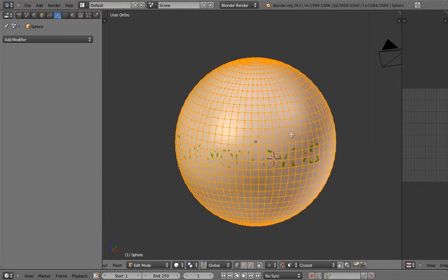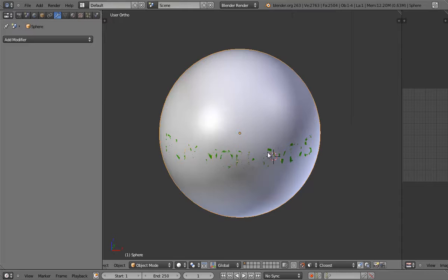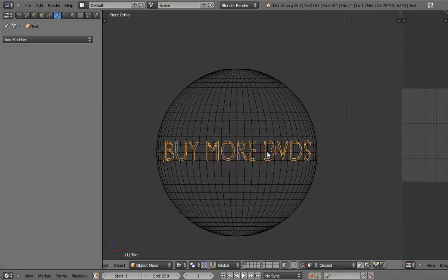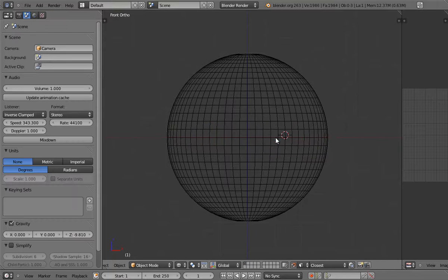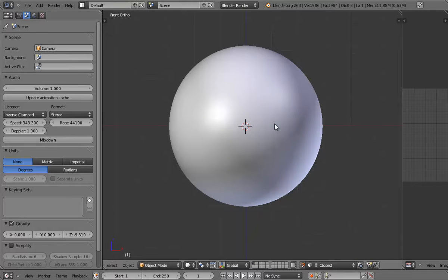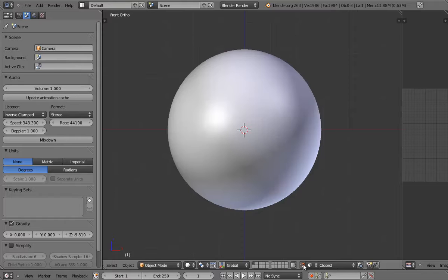Now let me show you how to cut a hole in the sphere. Now that we know the methods, we're going to use the same method. We're going to start from scratch. So I'm going to reset all of these tool options. In the header, I'm going to deselect that icon on the end. I'm going to change the snap element back to increment, and I'm going to turn off the magnet icon. So back to default settings.